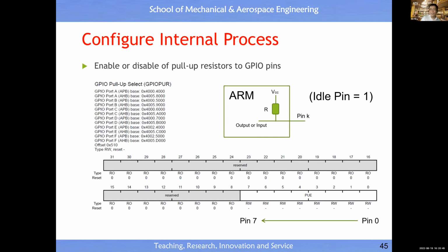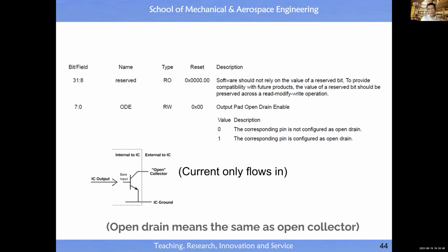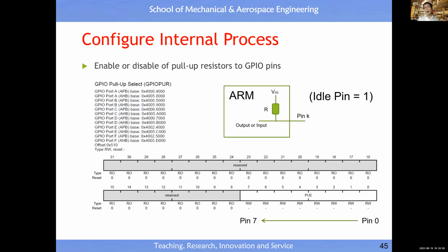This is for when you turn it on for a certain period of time dynamically; after that you must turn it off. If I want to output a signal, this is also for safety. If I do not output anything, the signal line will float there, depending on the noise. Sometimes it could be 3 volts or 2.7 volts.